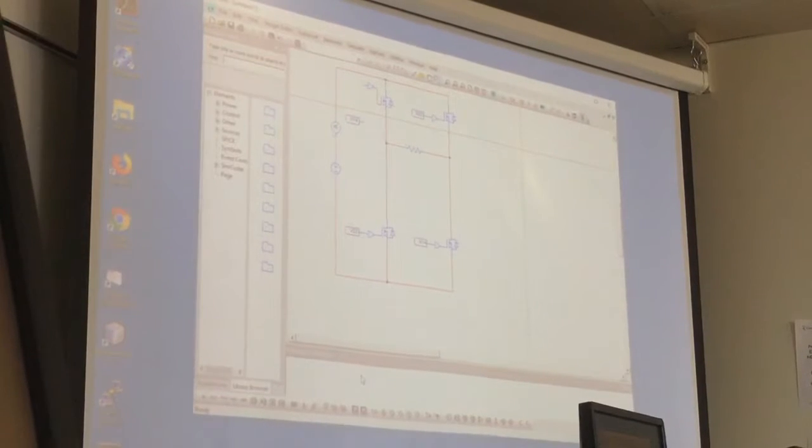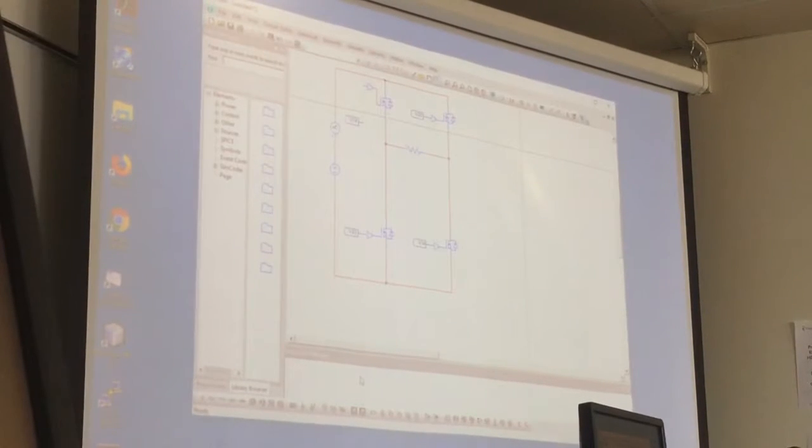But for example, here you have a signal to control your MOSFETs, let's say it's coming from a DSP or a computer, I don't know. You cannot plug this into your converter. So you need something to adapt this signal to the power level. And this is the function of this on-off controller. It shows, for example, that this label cannot be connected here.